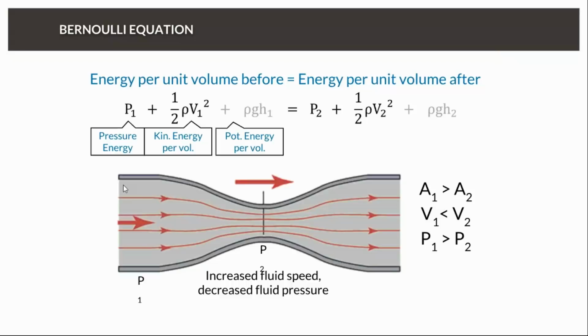As we said at the start, the two main generators of forces are the pressure and the viscous effects. Outside, let's say, globally, in the region where we can neglect the viscosity, the main effects will be pressure. And you see already the pressure is varying with velocity. So where we will manage to make the speed increase, we will manage to reduce the pressure and create suction. And this can be good, for instance, to pull the car down and to increase downforce.